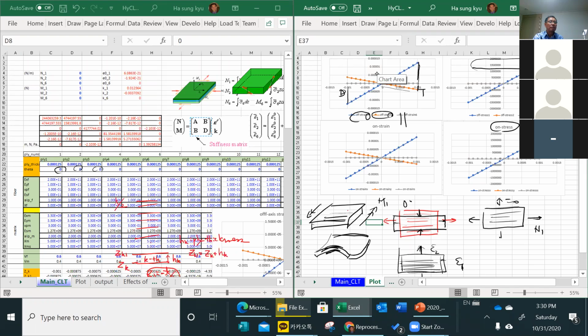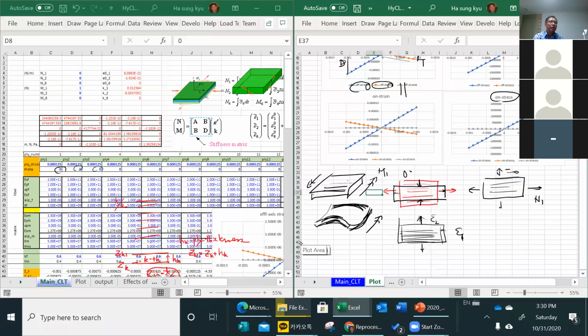So in a plate laminate, when we have bending in this way, it bends this way, but in this direction we're going to have a slight anti-curvature. And it's like beam theory, where we have an R, but in this curvature we have another R. This is the RY and this is RX.